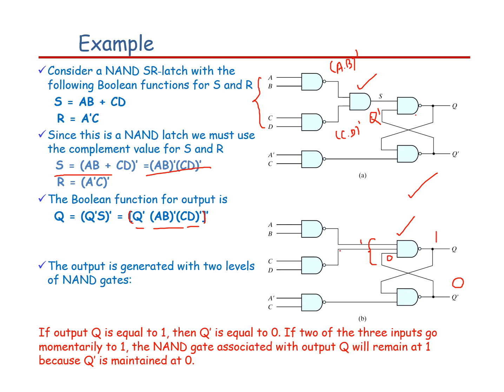That is why whatever the changes in any of the inputs A, B, C, D, that momentary change will not affect your output. Hence this will maintain the output, and the hazards can be reduced. That momentary change can be reduced when you use an SR latch. That is what is discussed here.